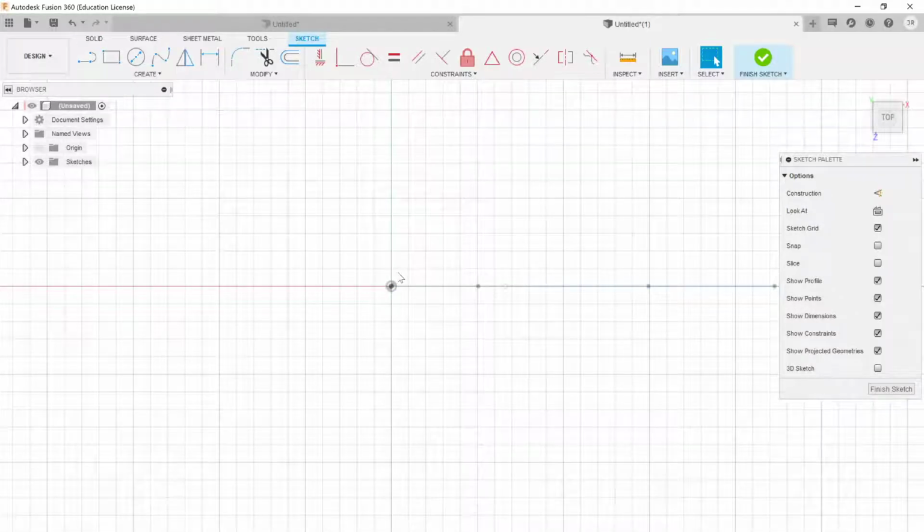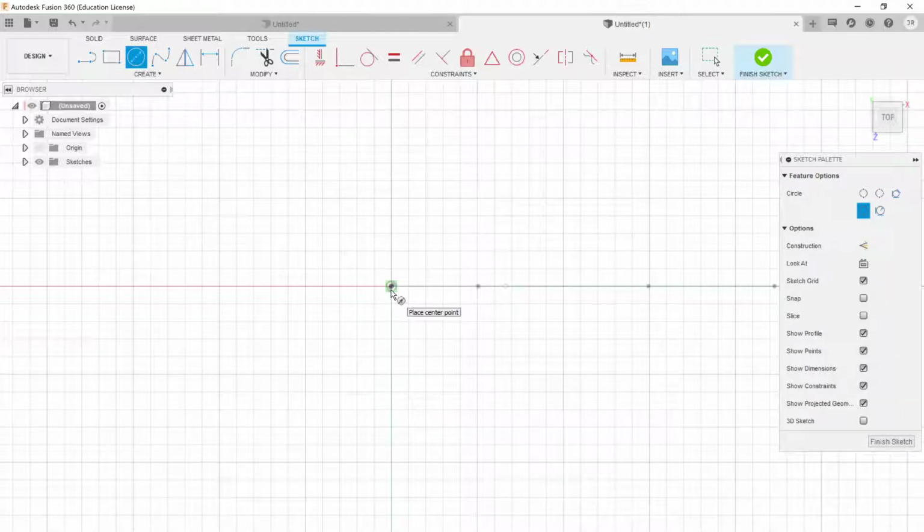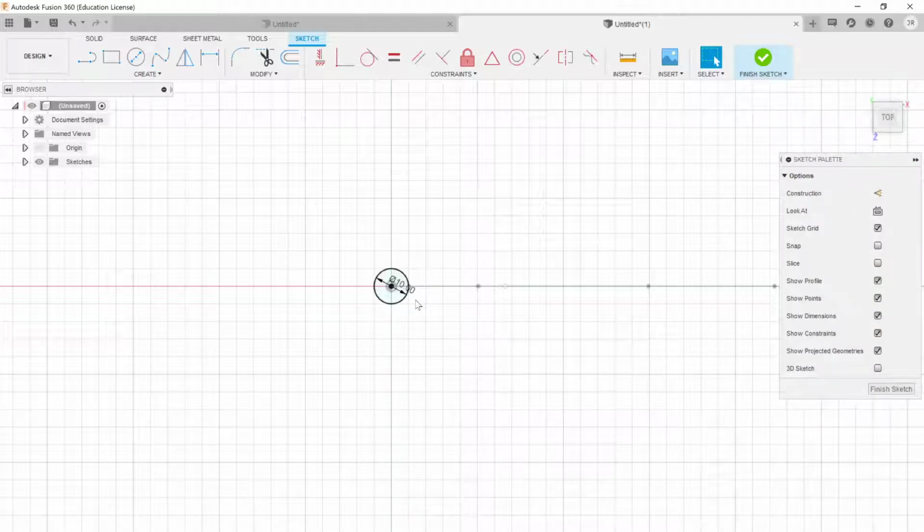So let's go. I'm going to use a circle. We could use any shape. Any closed sketch would work, but I'm going to use a circle because that tends to be easier to visualize and quickly produce. So let's make a circle. Let's make it just coincident with the origin, and let's not make it too thick, because if it is, it might overlap on itself, and we don't want that. So I'm going to go ahead and put 10 millimeters in thickness. So it's a pretty thin circle.